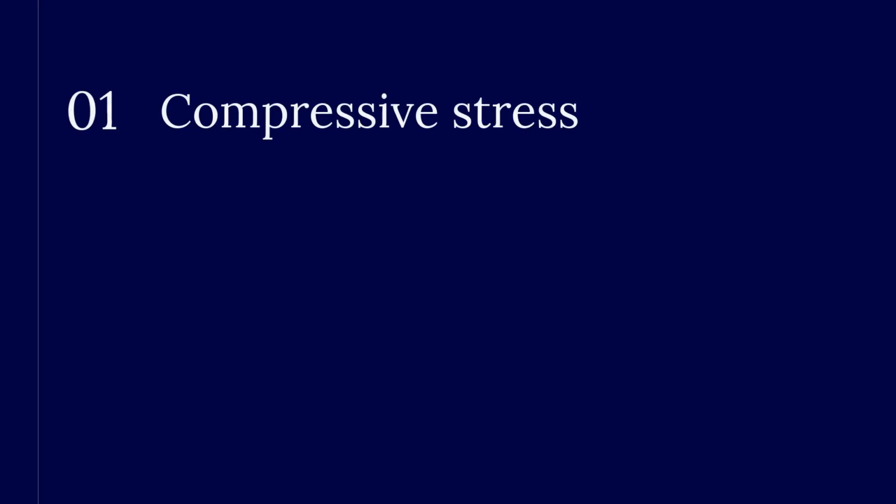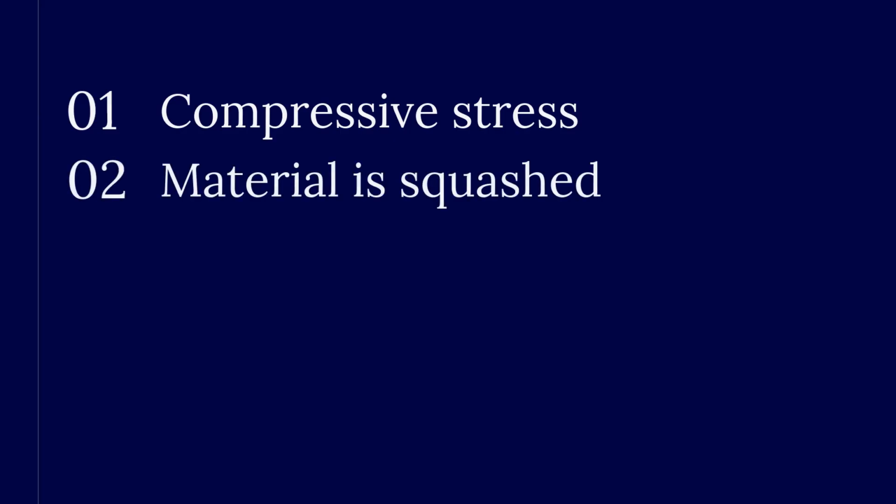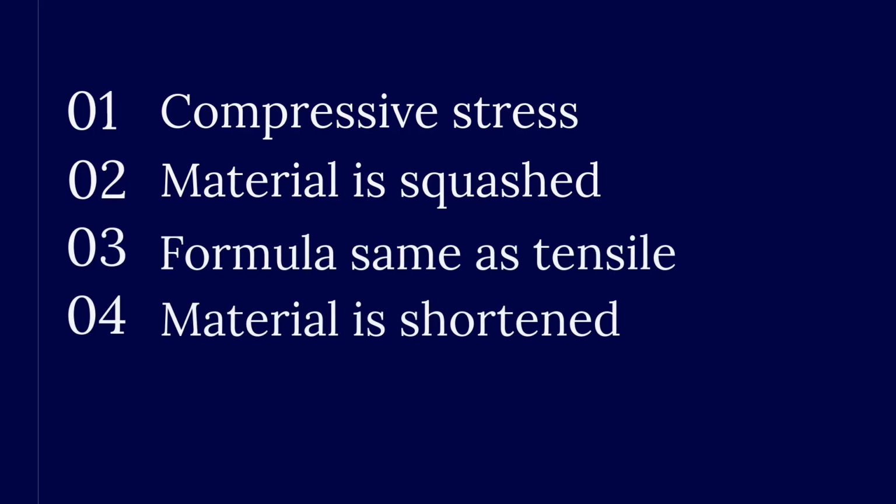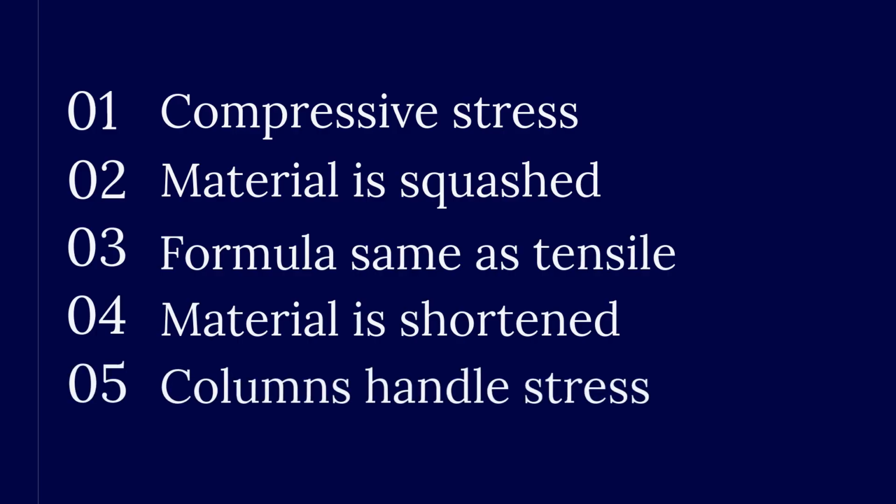Compressive stress occurs when a material is squashed. It uses the same formula as tensile stress. However, the material is shortened instead of lengthened. Structures like columns and bricks handle compressive stress. Understanding this helps in designing stable structures.